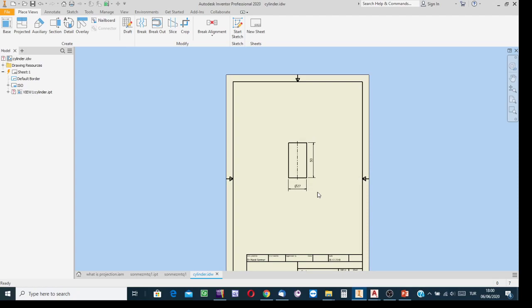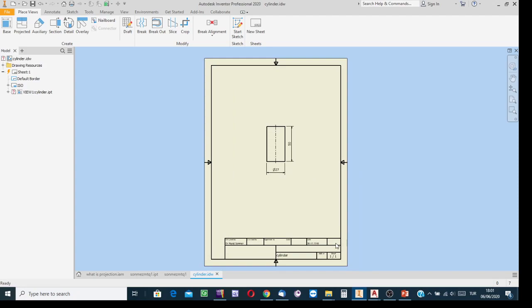Before saying something on the shape of the object, first see the title block and find the quadrant symbol there, whether it is the first quadrant symbol or the third quadrant symbol. But here in this school exercise, there is no quadrant symbol. Why? Because the teacher aims to test the learning outcome, whether although the quadrant symbol has been hidden, the student can say that it is a first quadrant projection.